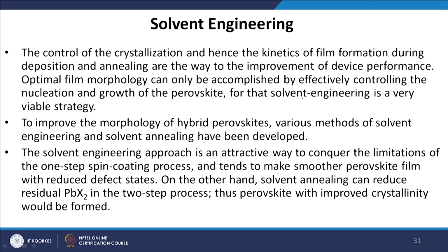Now, another important tuning parameter is solvent engineering. The crystallization, and hence the kinetics of the film growth, can be controlled by changing the solvent. To improve the morphology of the hybrid perovskite, various methods of solvent engineering and solvent annealing have been developed. The solvent engineering approach is an attractive way to overcome the limitation of the one step spin coating process and tends to make smoother perovskite films with reduced defect density.